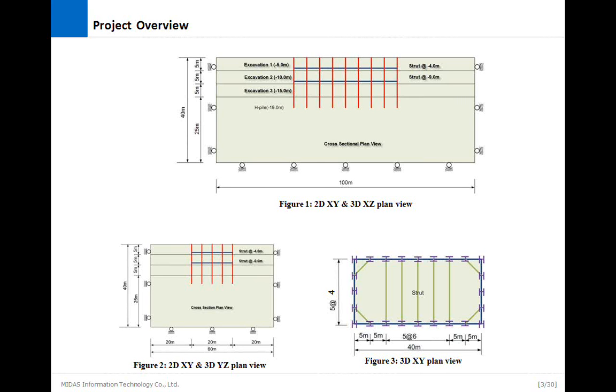So today I will be performing a semi-coupled deep excavation, by which I mean I will be performing stress analysis on the deep excavation, as well as a dewatering on it. This ground in front of you will be excavated in 3 layers: excavation 1, 2, and 3. Initially it has a total head of 40 at the top, which will reduce and level as we proceed with the excavation.